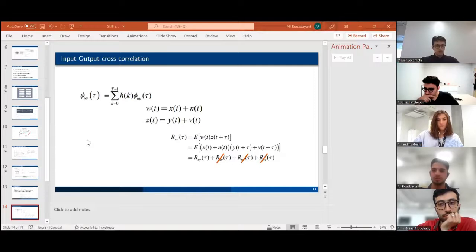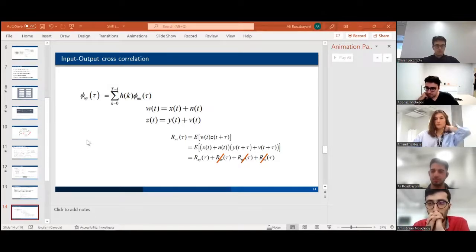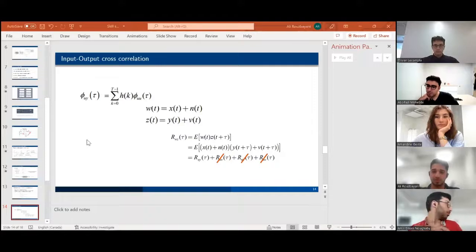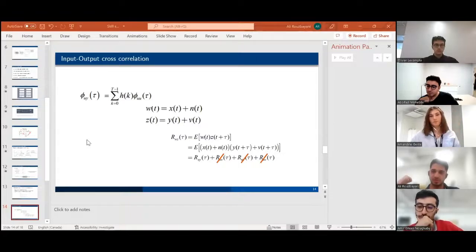So if we want to get the frequency response of a system, we give it all these different sinusoidals from like 1 hertz up to infinite gigahertz, not practically, but in theory. If we sum all these sinusoidals, we will get this constant number, which is the delta function in the frequency domain. So these two ideas are exactly the same idea, but this is the time domain version, and the frequency response is the frequency domain version of the same.